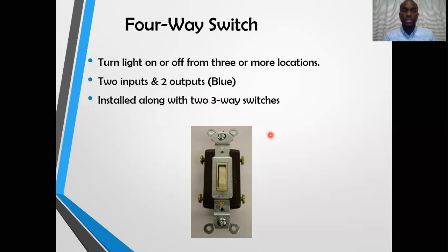We learned previously that three-way switches must be connected in pairs and they provide two locations for control. Adding a four-way switch to that combination creates three locations.